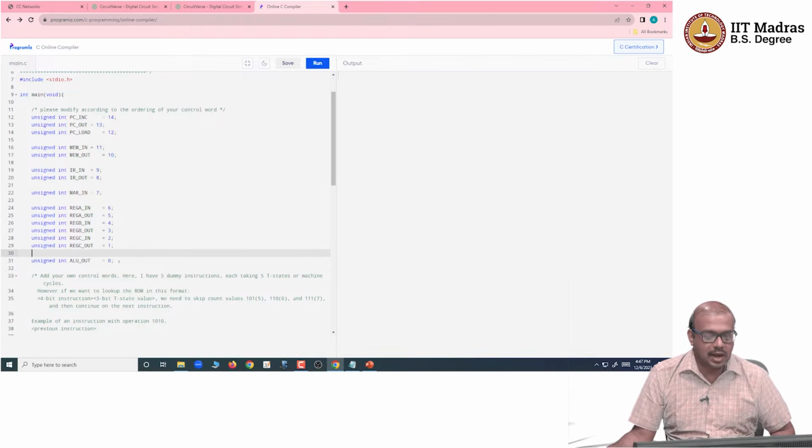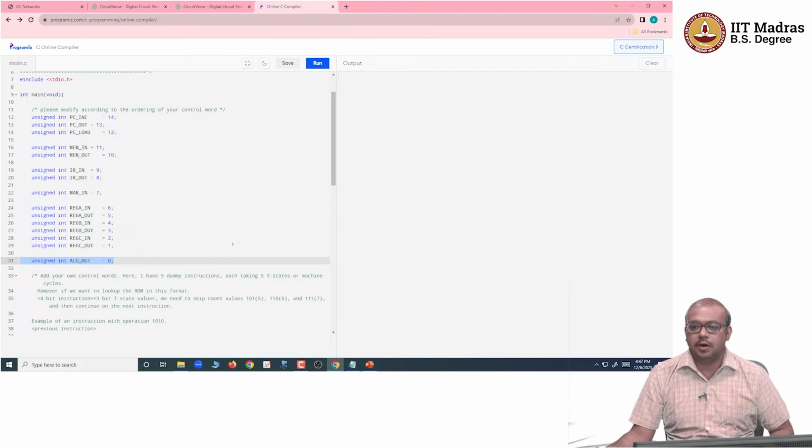ALU input is not necessary. As you can see, the ALU input in our architecture is already directly connected to two registers, A and B. If you had an option, then of course you would need to choose some kind of a multiplexer to know which registers from the register file are going to be used for ALU input.